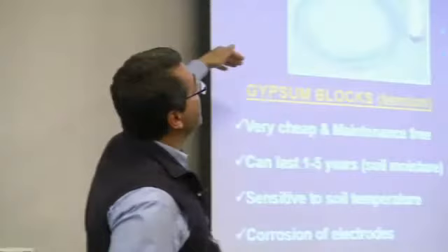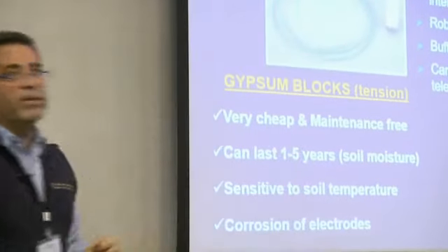soil. Okay. So there's a plethora of sensors on the market that can give you an idea of soil moisture content or soil moisture tension. In any case, they measure some specific characteristic of the soil, and then convert it into tension or volumetric water content through some calibration factor. The simplest ones are the gypsum blocks as a soil water tension tool, or sometimes we use the watermarks, and those have different advantages and disadvantages.